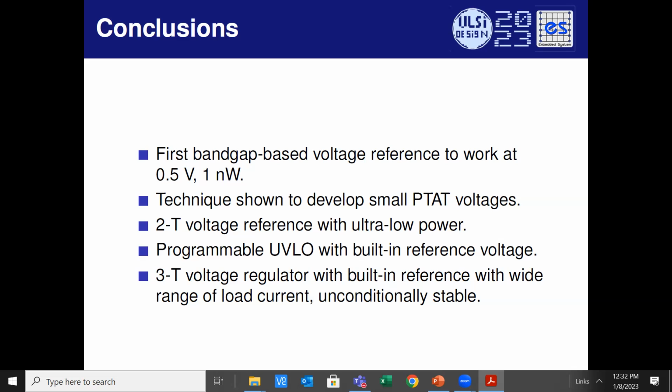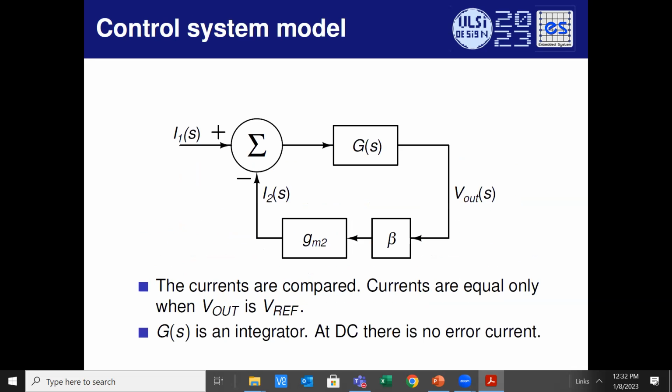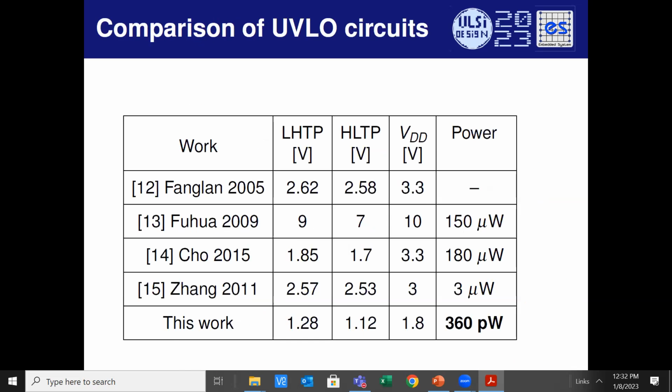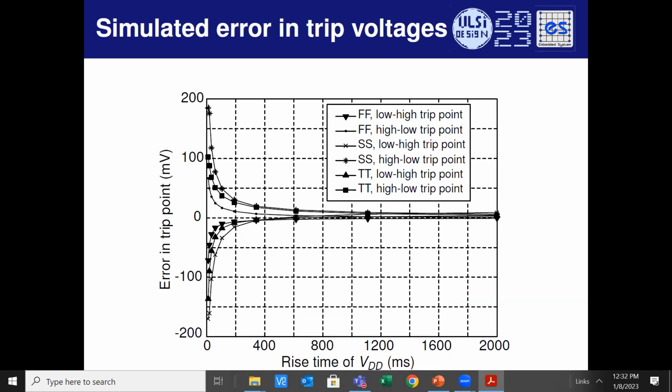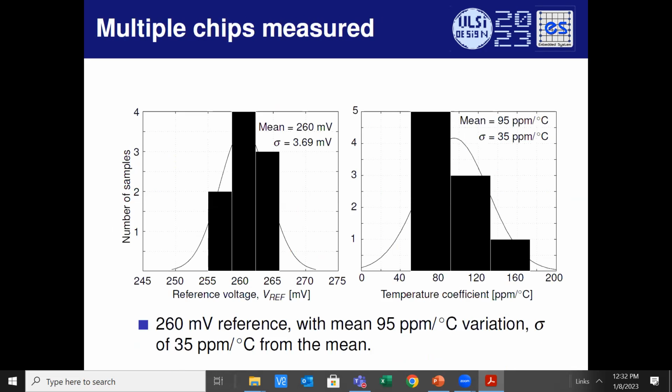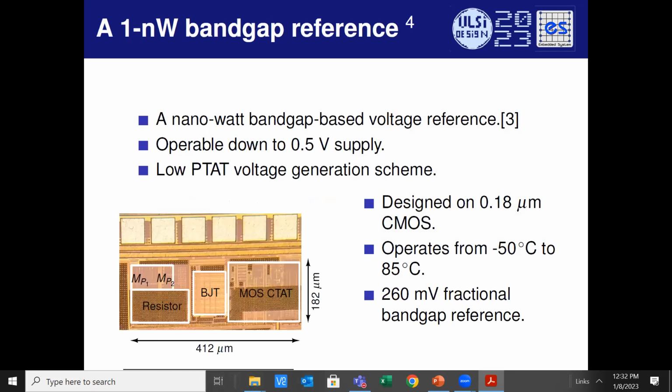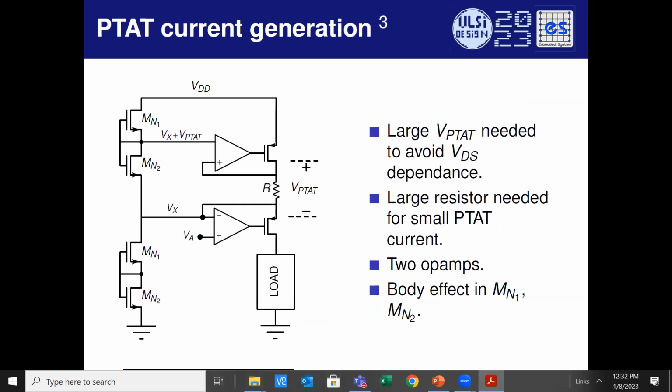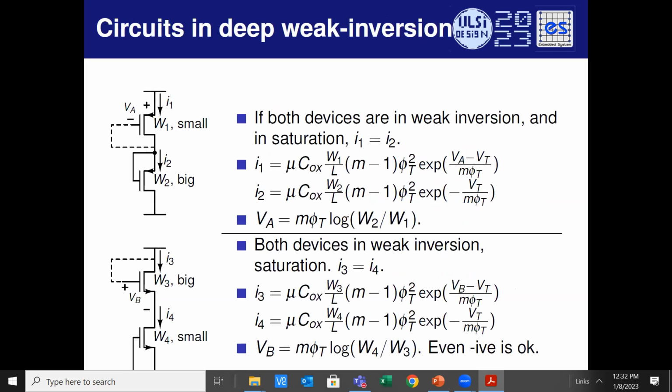Couple of questions regarding the PTAT circuit where both the transistors are the same. I'm just wondering, how do we control the slope and how is the slope compared to a normal PTAT slope? Is it comparable? Okay, it's just by sizing the W.